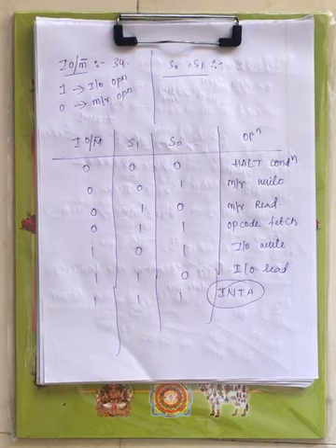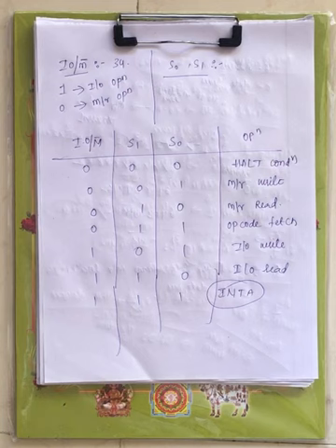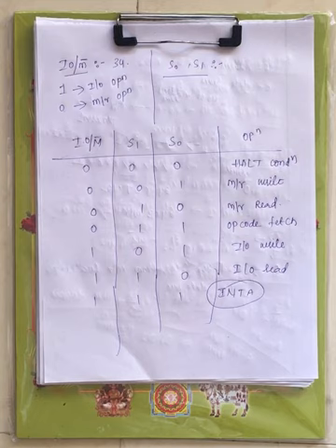When it is 1 0 1, IO write operation. When it is 1 1 0, IO read operation. When all are ones, interrupt acknowledgement signal. What is meant by acknowledgement? To accept. Interrupt acknowledgement is nothing but the interrupt signal. We have different types of interrupt signal. Whichever of those 5 it may be, that particular signal is accepted by the processor, which is nothing but the interrupt acknowledgement signal. Now this is about IO slash memory bar and S0 and S1.